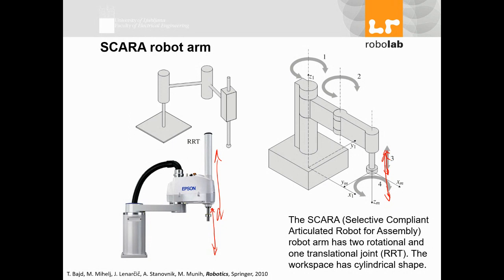Okay, so one of the differences would be, Nikita says, to move SCARA linearly, we need to actuate two actuators, while in a cylindrical arm, we need to actuate only one. Linearly, what do you mean by linearly? You mean the pathway, right? The end effector pathway. You want to move it from here to here. Yes. Okay, that's actually one of the points which I'm trying to make.